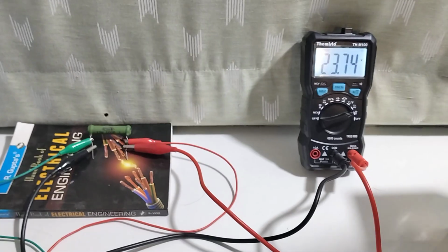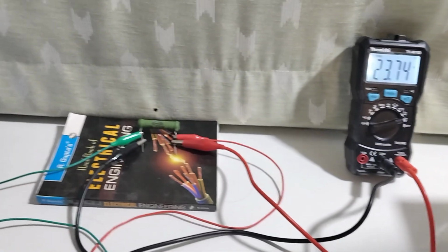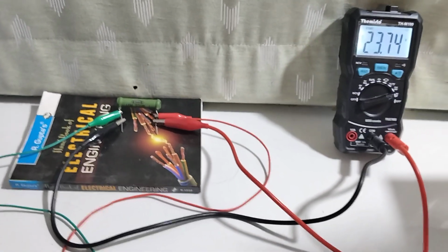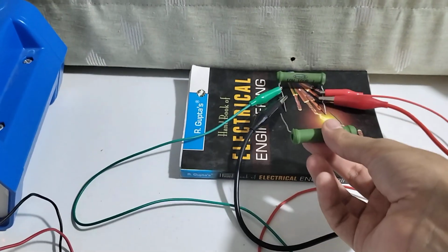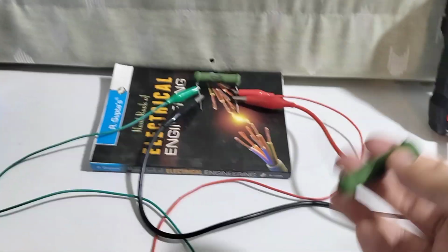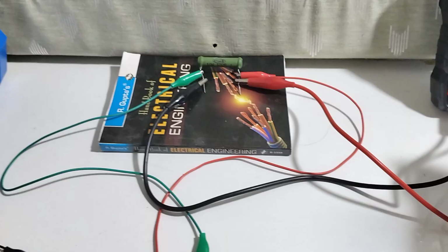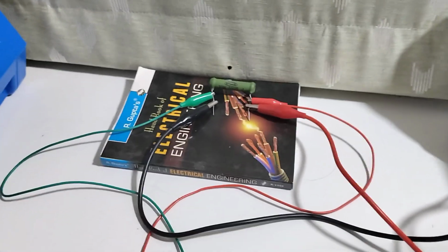And just to demonstrate how it can dynamically change its duty cycle, I have another load here, another 100 ohm. I'm just going to be touching this and putting it in parallel with the current 100 ohm, which would basically bring down the load to 50 ohm and draw double the current. And let's see how it handles that.